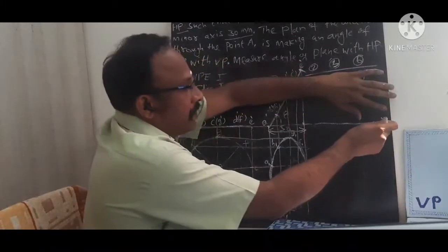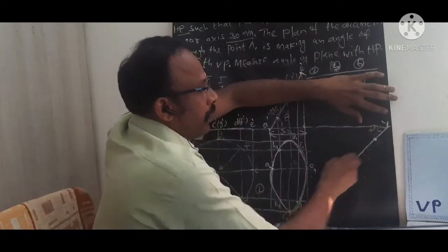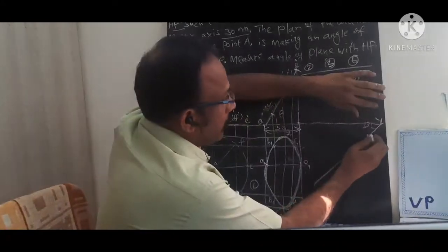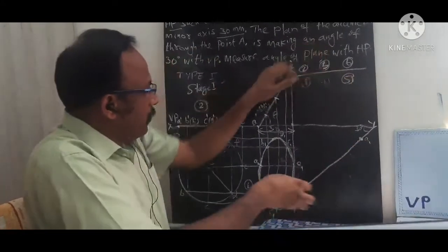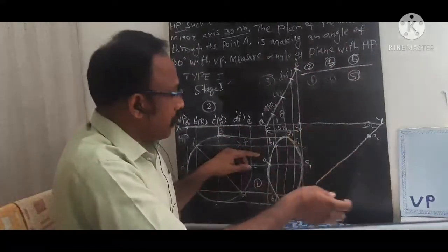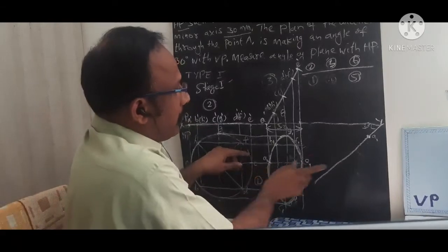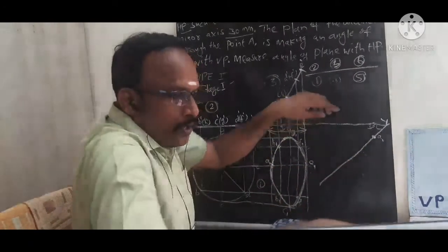You can draw this inclined line 30 degree on right to left or left to right. Both are okay, acceptable. Now this is the point A1. Now from A1 you can take the compass. Now you know this even distance also, right? So from A1 you need to mark.